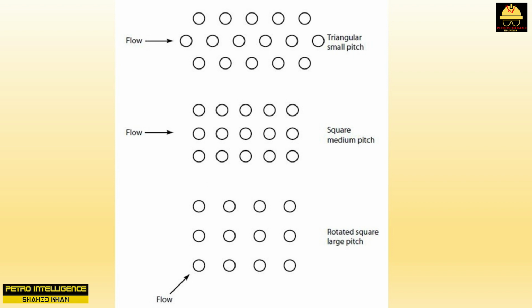The advantages of this tube pitch are: many tubes are squeezed into a small shell ID. The tube spacing promotes turbulence and hence good heat transfer. This all results in reduced capital cost. The disadvantage of this tube pitch is that, except for the outer few rows of tubes, the shell side cannot be cleaned by hydroblasting. Obviously, this sort of arrangement should never be used in a fouling service, unless the deposits can be chemically removed. The second example shown in the picture is 0.75-inch tubes, also set on a 1-inch spacing.